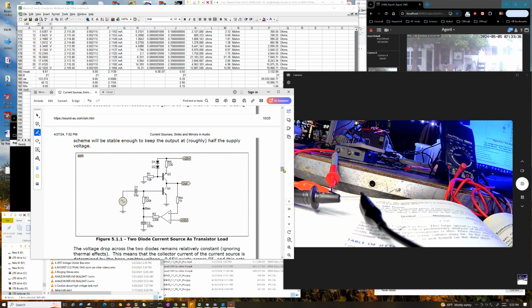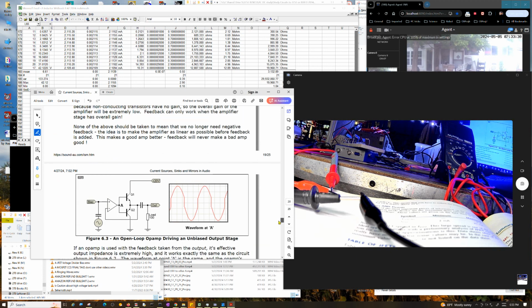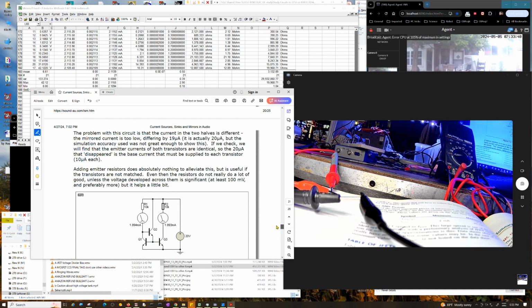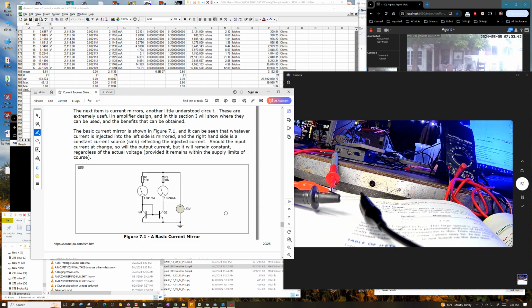But I did have one other thing I wanted to say on the current mirror thing. It occurred to me that basically the current on this side controls the current on that side, right? Well, as I've demonstrated on the FET circuit, the voltage on your control transistor doesn't have to be the same as the voltage on your load transistor.